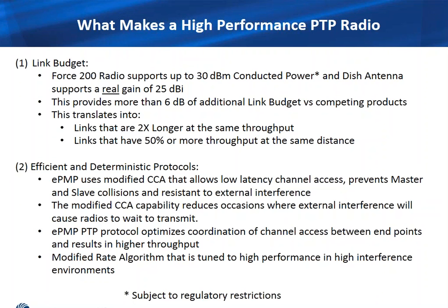And then on top of that, over quite a bit of experimentation and field test, we have optimized what's called our rate adapt algorithms, so that we're choosing the right modulations to use for the environment that we're operating in. Choosing the wrong rate algorithm will either result in excessive retransmissions, which can impact performance, or operating below the optimal throughput that could be achieved in certain environments. So both those things together make for a very high performance point-to-point radio, and you'll be very pleased with the performance you get from the Force 200.